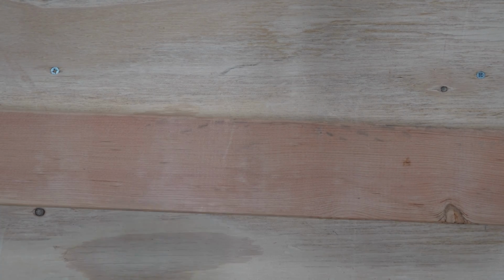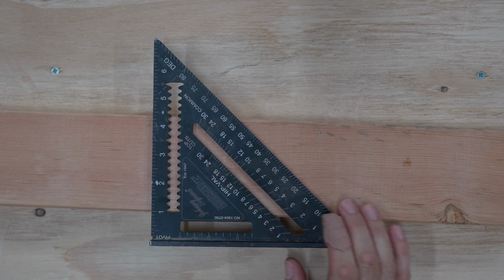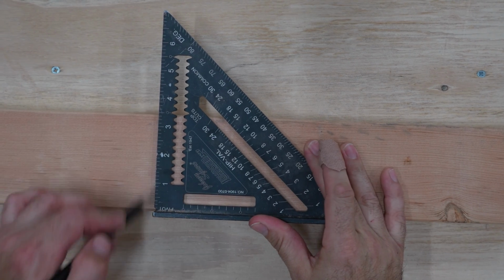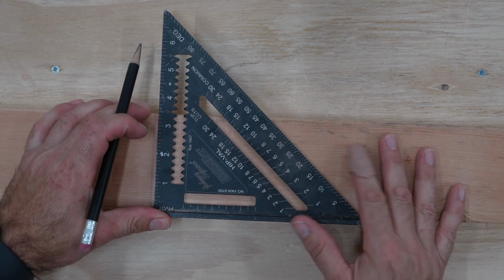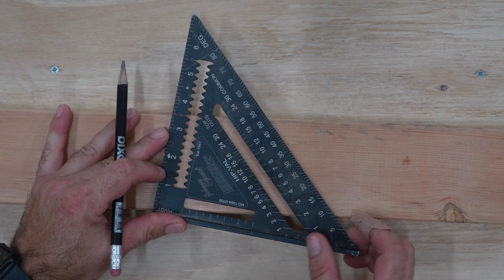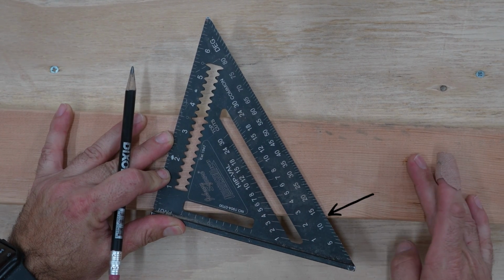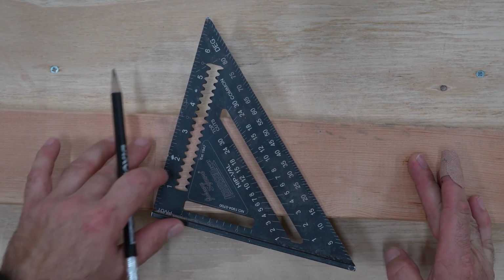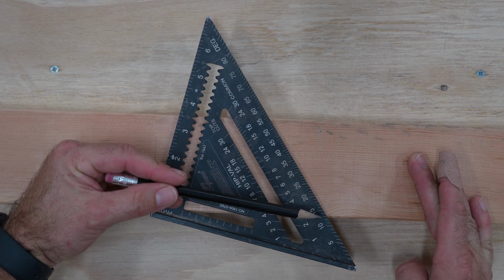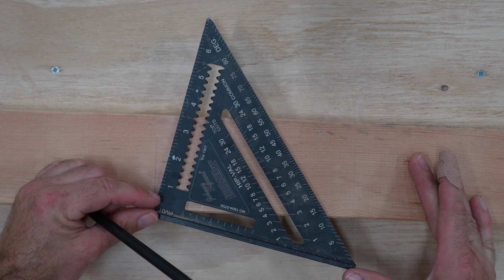One thing I forgot to mention is that if you use a speed square to lay the hip rafters out to make the plumb cut, you use the speed square like we did in the last video, but for the hip, you swivel it to the 4/12 hip valley mark. When you do that, you can see that the angle of the hip is 13 point something, which is the angle of the hip and the angle of the plumb cut for the hip. And if you remember, the actual angle is 13.27, which we calculated earlier.